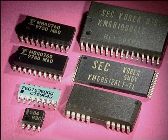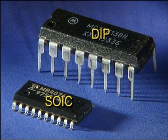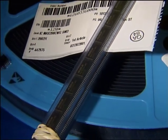At this point, let's take a look at the smaller scale ICs. These undersized packages with leads on 2 sides are called Small Outline Integrated Circuits, or SOICs. SOICs are the surface mount equivalents of through-hole dips. These components come from the manufacturer in tubes, or on tape and reel.